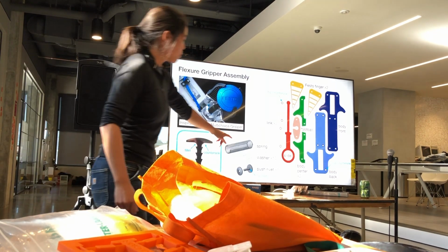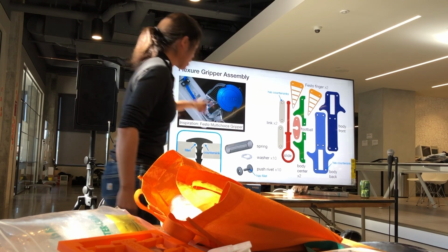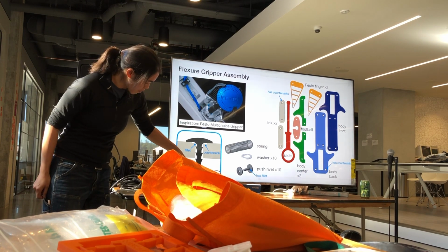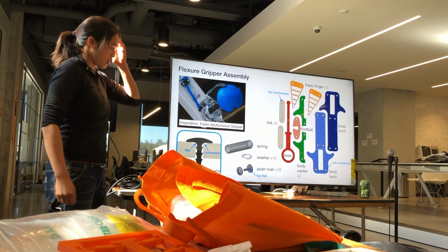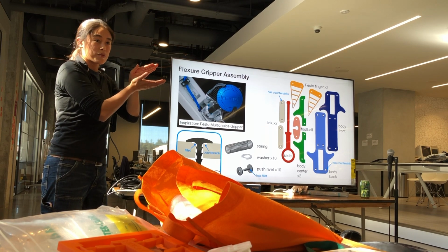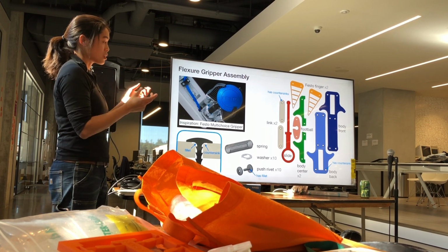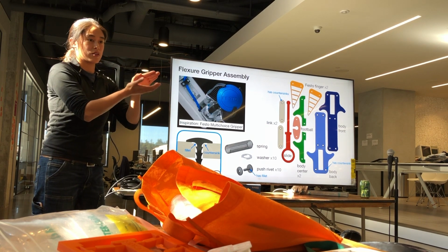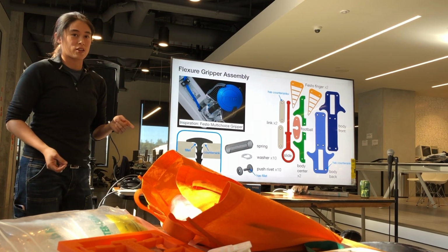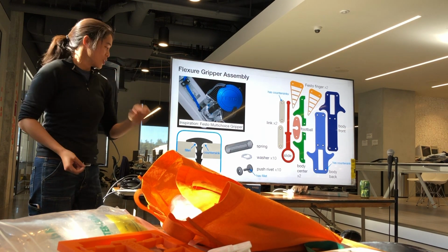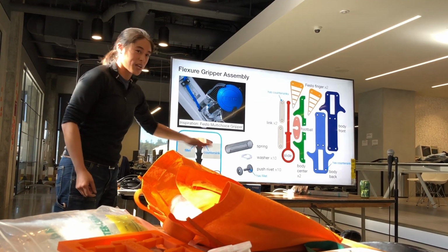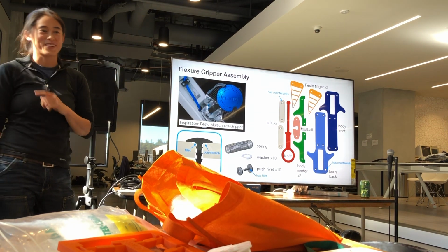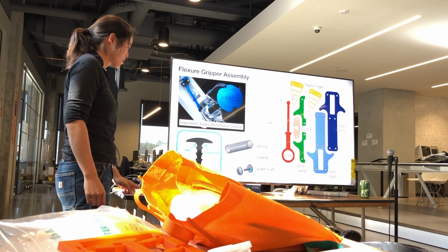So when you get your parts, make sure that you're looking for those, and that's the side that the rivet head goes to. Finally, the rivets have teeth on them, so they only lock incrementally, and because of the thickness of the materials I'm using, I couldn't get it to lock exactly at the right increment. So there are washers included to add up to the right thickness stack. Put in this rivet, do whatever stack of materials, then put a little washer on it. Again, if you forget the washer, it's still going to work. It'll just work nicer with the washer in place.